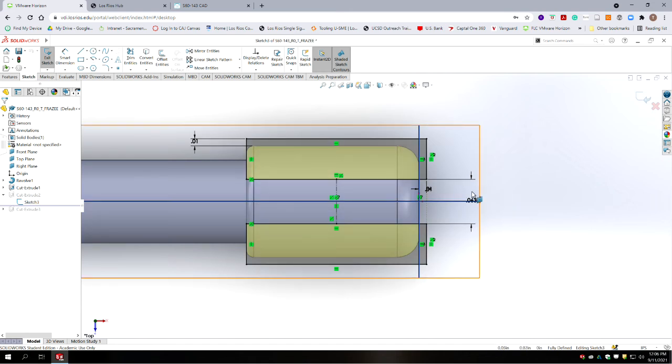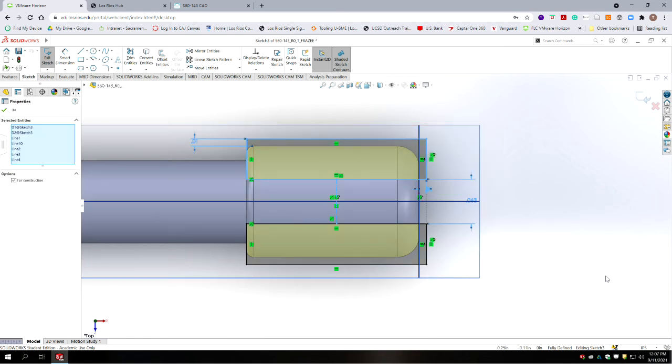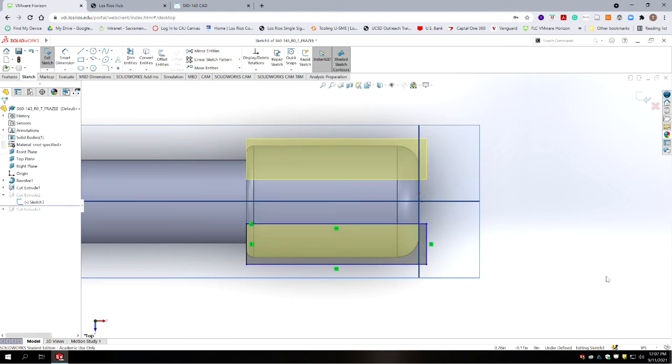So what we'll do is you're going to click out in space and then drag the cursor so you get a marquee box that envelops the items in the top of the viewing plane. And we're going to hit the delete key on our keyboard and delete those features.